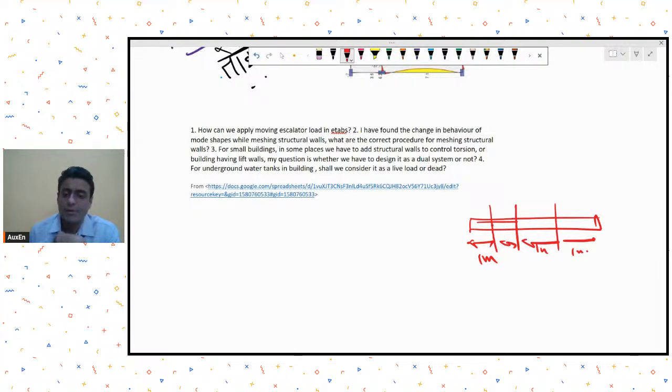That is my view. Along the plan length, you may mesh it at around every 1 meter. It's a good mesh size to have. If you want to find the optimum mesh size, you can go for two or three trials where you change the mesh size, observe the change in output, and accordingly decide the optimum mesh size to keep.